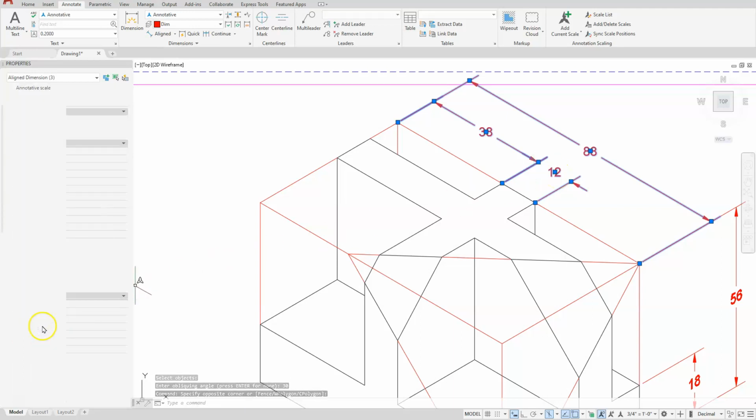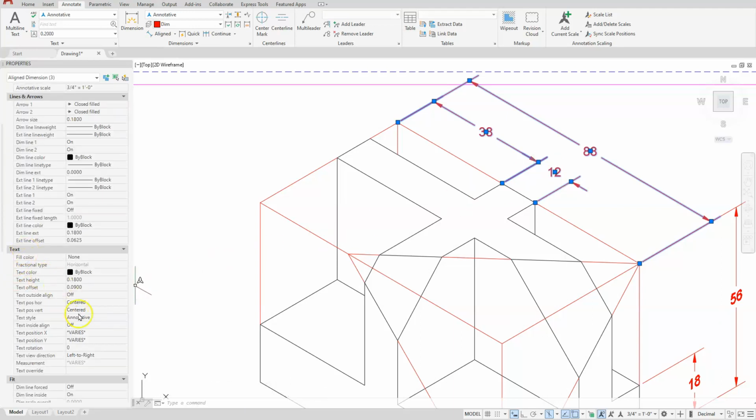Go over to the properties. Find text. I'm looking for the rotation. Now you can see in this one, 30 is kicking us kind of the other way. So when you see it doing that way, usually just type in -30. So you have 2 choices in my opinion, 30 or -30.